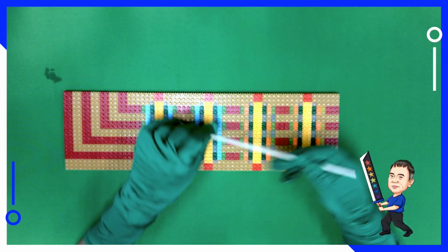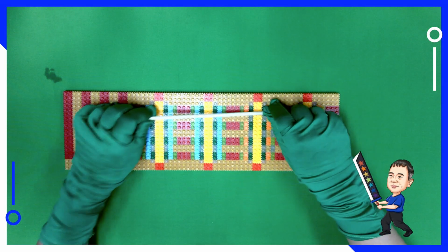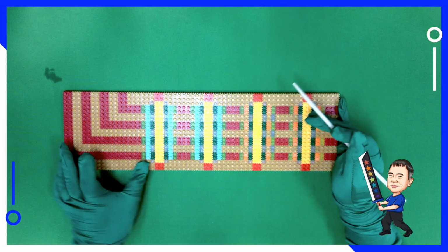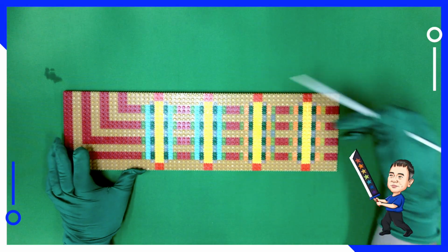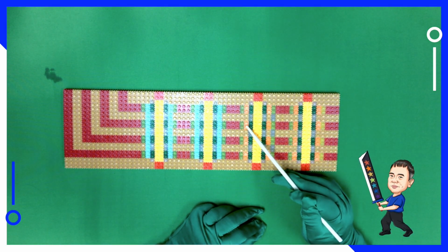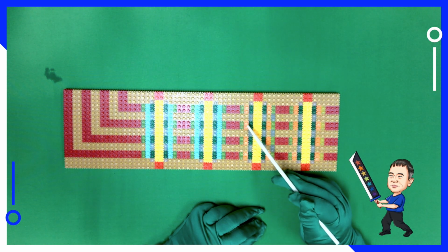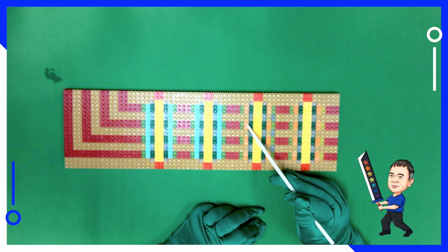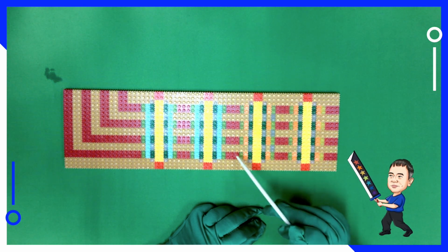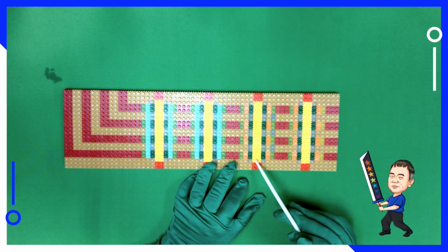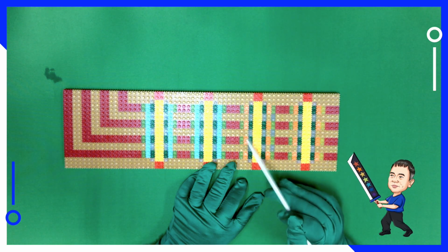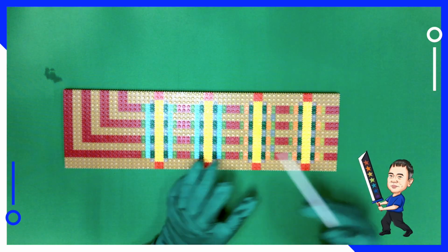This is a word line. The word line covers lots of cells. Then the cell information will come out from the bit line. So this is a word line, and this is a bit line. So the first thing I do, if I want to get the information of the second cell here, is I apply a voltage high enough on the first, third, and fourth. So the current will always go through no matter the information on the first, third, and fourth anyway.